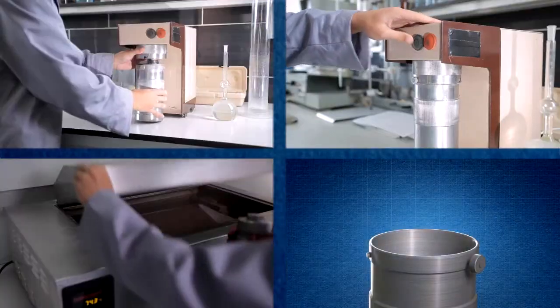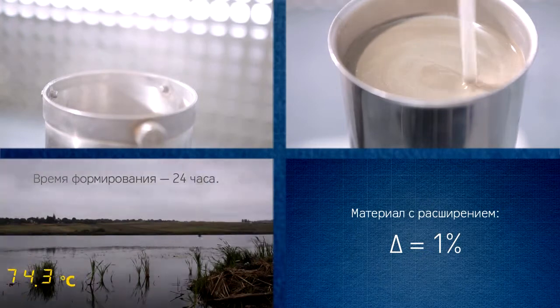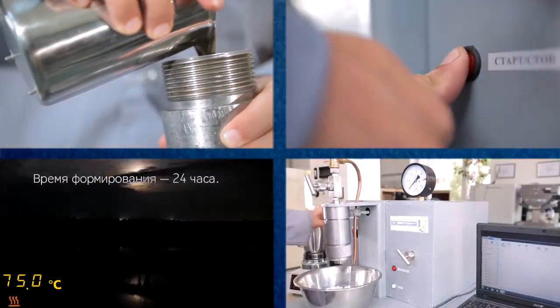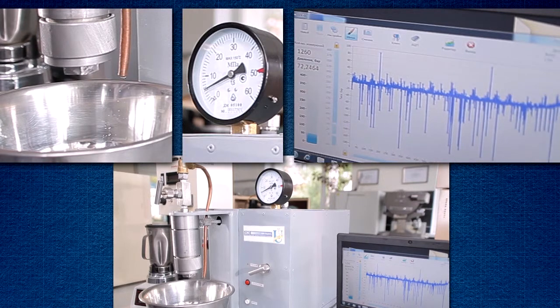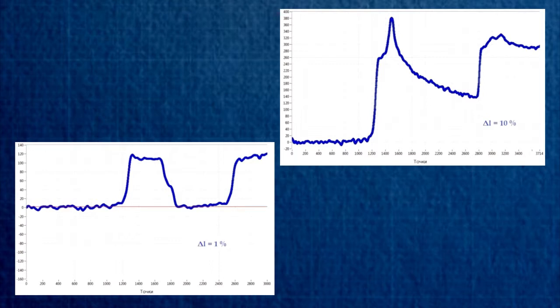The OGK-01 device is a hydraulic machine allowing to inject a working fluid into the test cell with a given performance to record the variation of pressure. The water is pumped through the filter system in the holding tank and then is pumped into the test cell. The test cell is a specially designed hollow cylinder made of high-alloy stainless steel, closed with special covers on both sides. As a result of a constant fluid supply, the pressure in the cell increases and leads to breakout of the contact between the cement stone and the test cell wall. The breakthrough pressure is recorded in the computer program.